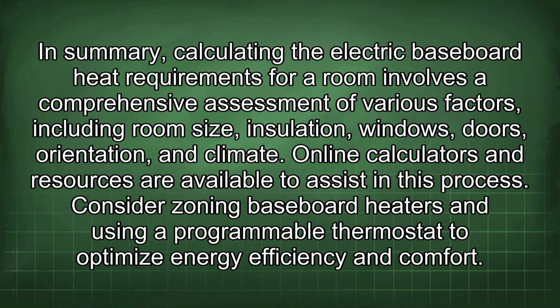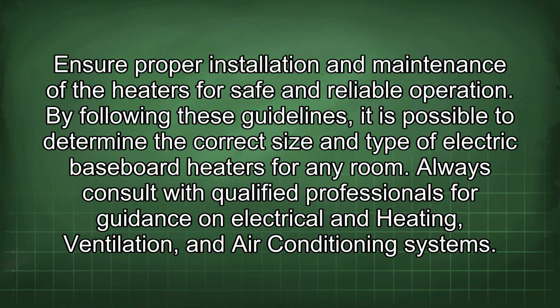In summary, calculating the electric baseboard heat requirements for a room involves a comprehensive assessment of various factors, including room size, insulation, windows, doors, orientation, and climate. Online calculators and resources are available to assist in this process. Consider zoning baseboard heaters and using a programmable thermostat to optimize energy efficiency and comfort. Ensure proper installation and maintenance of the heaters for safe and reliable operation.